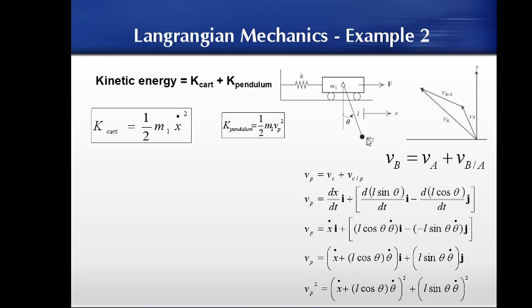So here you can see along the x you have the sine component. L cos theta is in the minus direction and L sin theta is in the x direction. So I am going to say that the velocity component along the x direction is d by dt of the x component, that is L sin theta, times i cap, minus d by dt of the y component. I have said minus because I can see that L cos theta, which is a y component, is in the minus y direction. So minus d by dt of L cos theta times the j vector.